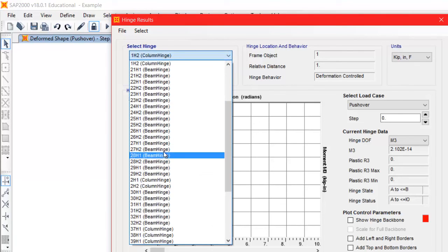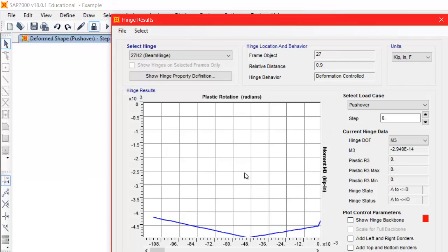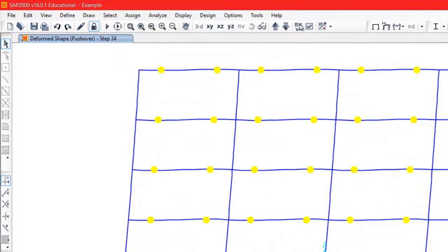If I look at the beams, of course you need to move a little bit, and then you can see at which point you reach any given performance state. You need to get out the values for the displacement at each floor. You need to calculate the drift at each story. You need to plot the profiles for the drifts and the profiles for the displacement.